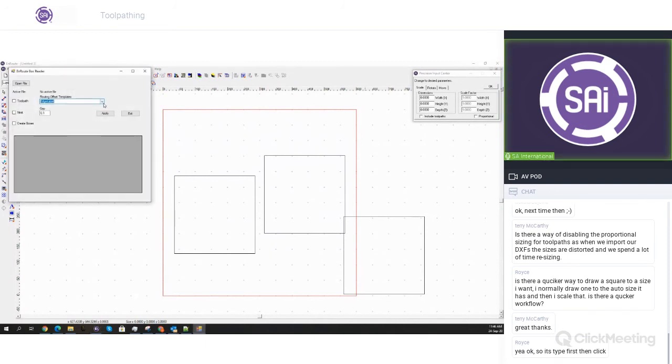So here you could enter an Excel sheet, which includes the width and height of your boxes, and it'll generate them all automatically in EnRoute. And you have the possibility to toolpath them as well with whatever strategy you have predefined, and you can choose to use the block nester to nest them at the same time as they're imported as well.